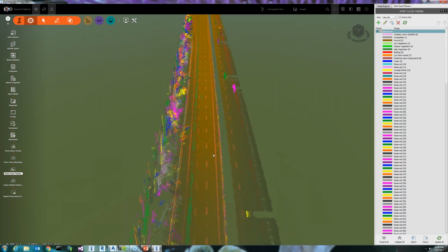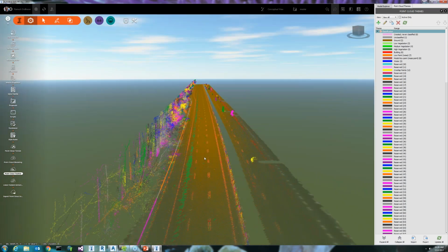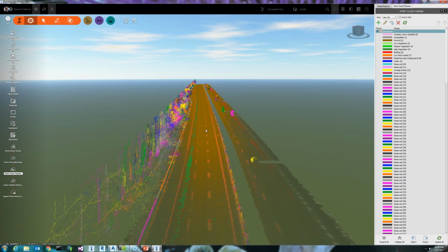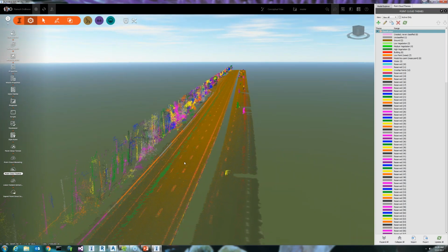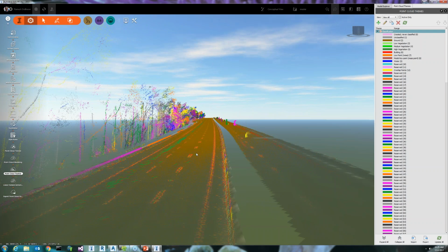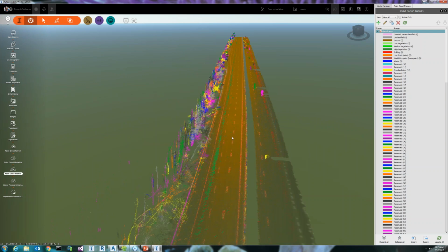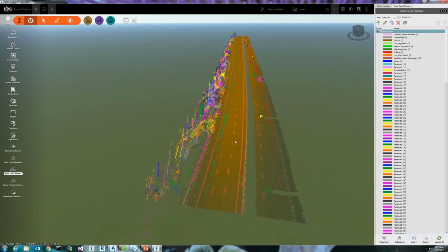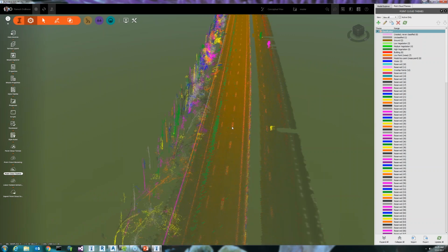Now you can see what it did internally. You can see all the brown points, the bare earth. You can see the software tried to identify the paint stripes and everything in there, and it also tried to classify the trees even though the trees don't have proper ground. Then maybe in a real project you might trim those things out, you don't need them, but you can also see the cars and everything. I think this data set is about probably a kilometer or a mile or something. You did a good job on classifying and flagging the information here.